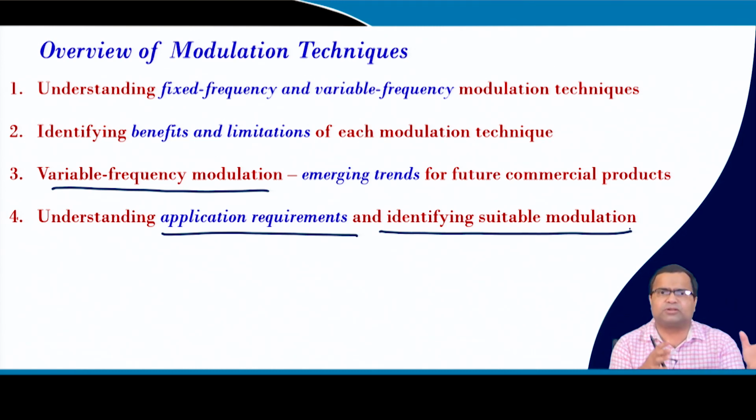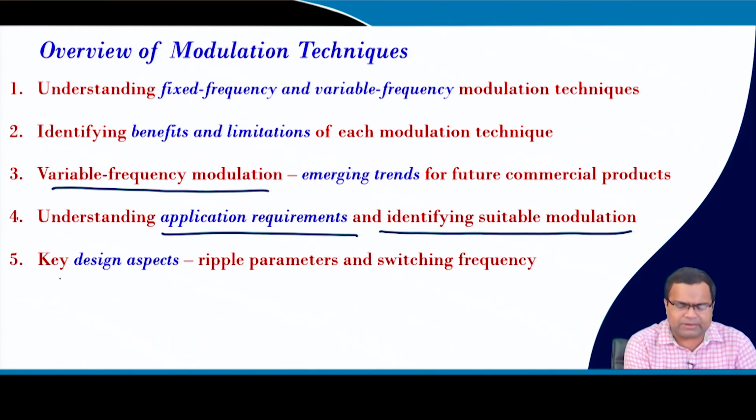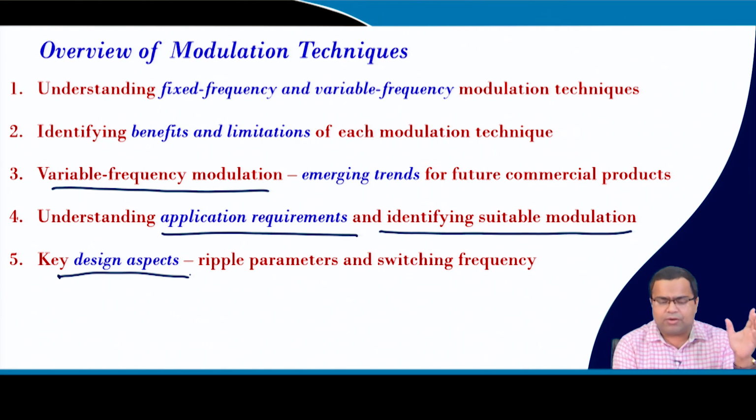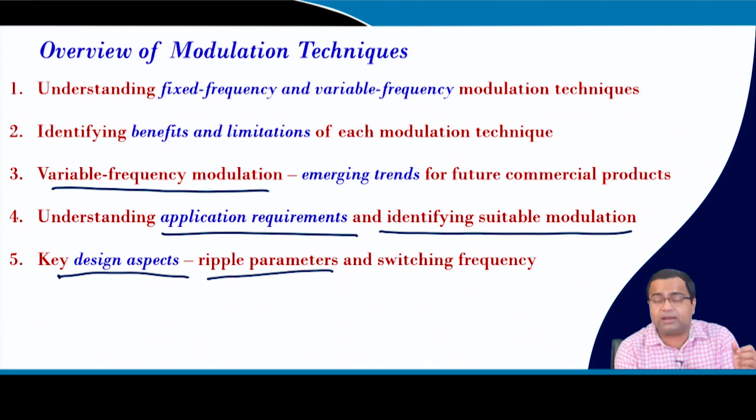But otherwise, in most cases we talk about only fixed frequency modulation, but this whole range of modulation techniques that we have learned will be useful to decide which one to select based on the application requirement. Then we also learned some key design aspects. When we select one modulation technique, our next question is how to design the power stage, because we need to take care of the ripple aspect, as this is directly related to our ripple specification as well as conduction loss.